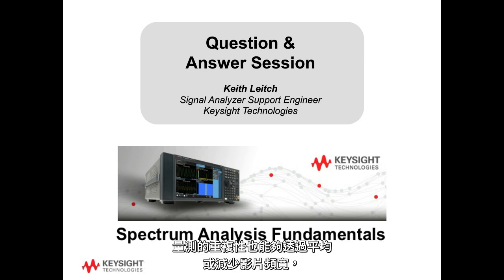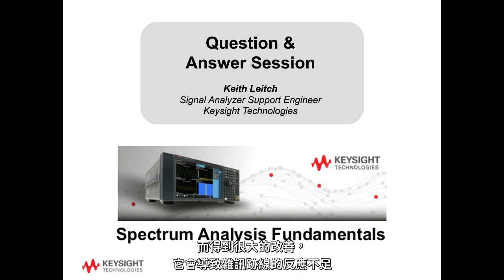Measurement repeatability can also be improved by applying averaging or reducing video bandwidth. Log video averaging can also be used. It causes an under-response in the noise trace, thereby improving the signal-to-noise of the distortion products.